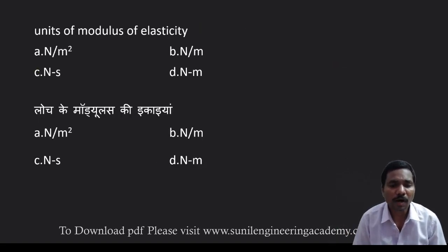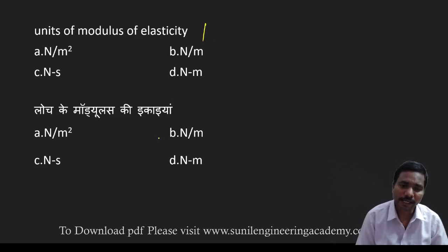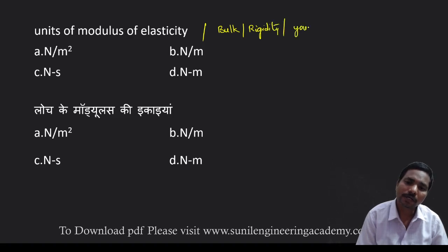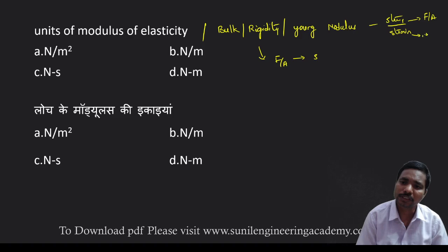Modulus of elasticity. In the theory class I have given modulus of elasticity, whether it may be bulk modulus, rigidity modulus or Young modulus. Whatever it may be, the units are the same as pressure: force by unit area, or stress by strain. Stress is force by unit area, strain has no units.